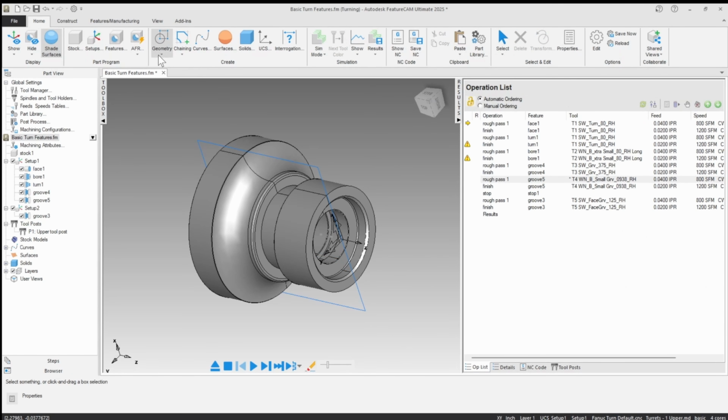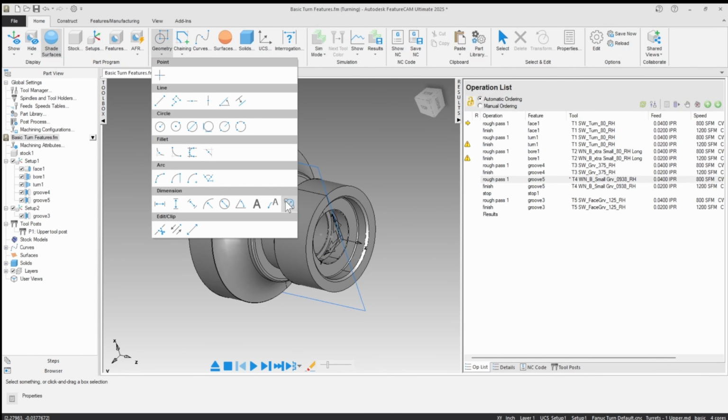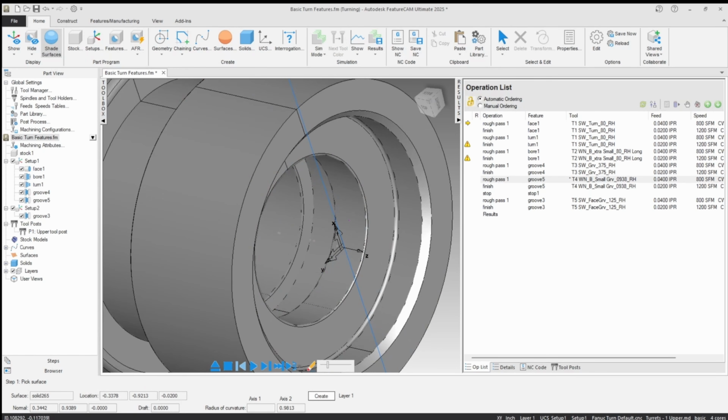So I'm going to show you one of the tools we have in dimensioning called curvature, where you click on that, and as you move on the model, you can see a green circle. If you look down here at the bottom, under where axis 2 is, when I have my mouse in there, you'll see that I have a 496.9. So that's a radius. So we're just under an inch with this. Okay, so I'll do like a 7/8 drill in here.